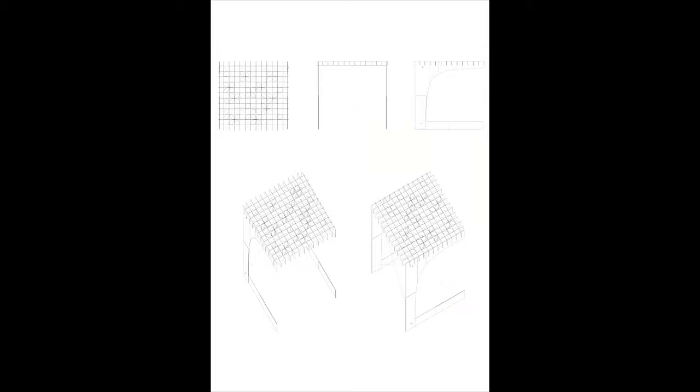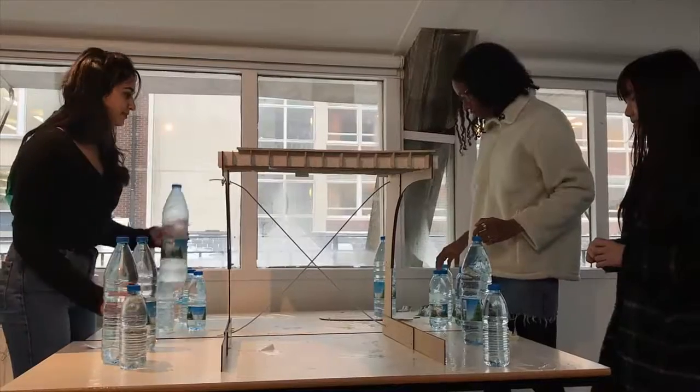To make it fit within the box, we made it out of 16 different pieces of MDF that we assembled with bolts, and in the back we added reinforcement with wires to create tension to prevent deflection of the two legs. But our mistake here is that we should have added one in a horizontal position to prevent deflection and buckling.